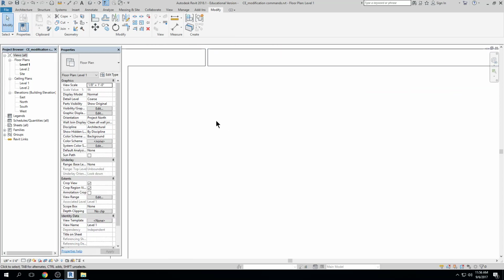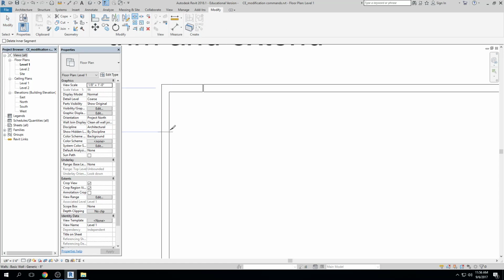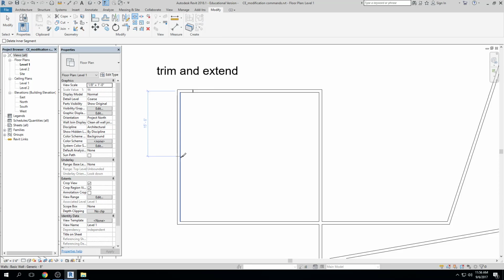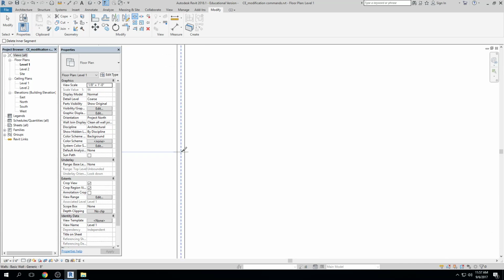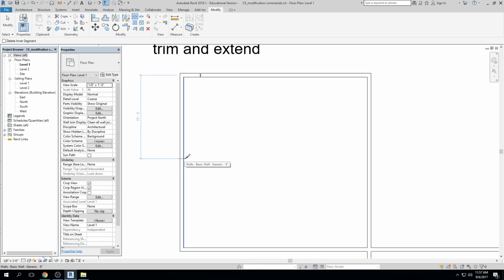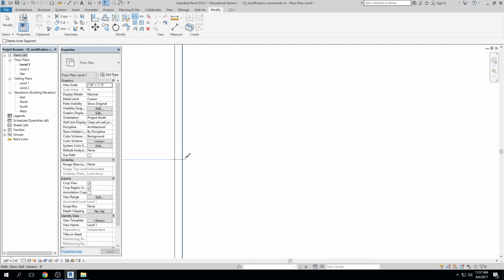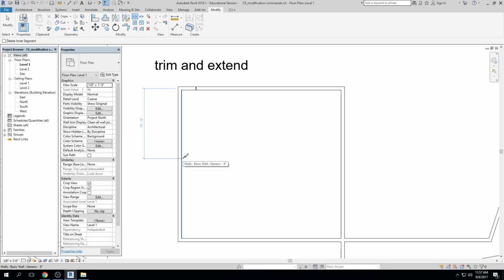Would it give you the highlight, the midpoint or something? You can, yeah. So if I click on split, you should be able to grab the midpoint. Ooh, let's force it. If you right click, ooh, that's not showing it. Good question. I remember being able to grab the midpoint. I'm thinking it's snapping to the midpoint, but it's not showing the midpoint. It seems like it flips when you hit the midpoint. Yeah, it kind of snaps to it a little bit, like you feel it, you don't feel it, but you can see 15.6 and then it flips to the other side. Yeah. If we want to make sure, it's not showing me the midpoint, okay, I don't really like that very much, but if we needed to find the exact midpoint, there are some other ways of doing it.